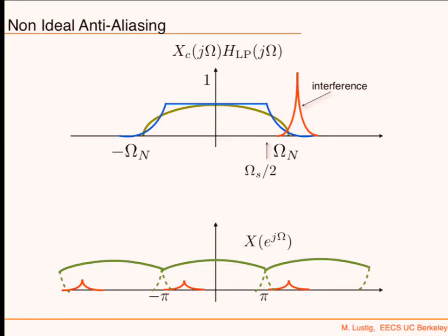So it's a real phenomenon that you have to deal with, and you deal with it by expanding your bandwidth. If I didn't expand my bandwidth, and I had a pretty high bandwidth of the signal, then, for example, if I only sample at 200 kilohertz, I would definitely get aliasing coming into the signal of interest. But if I oversample, I can push those away.